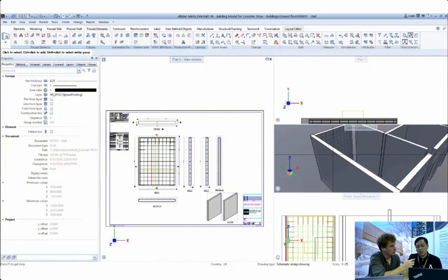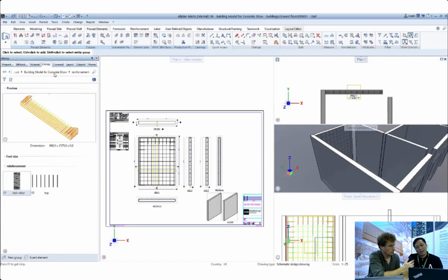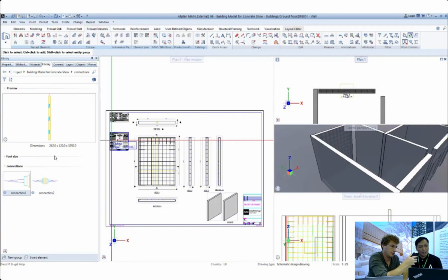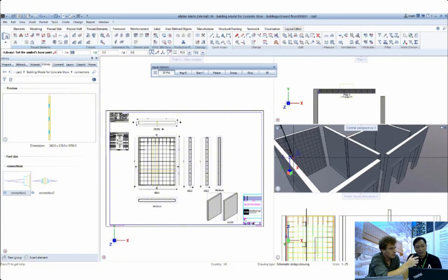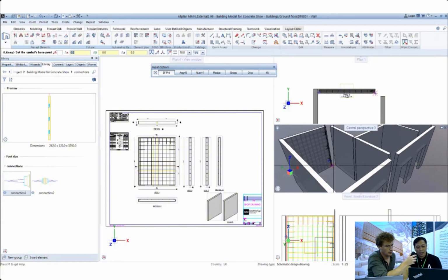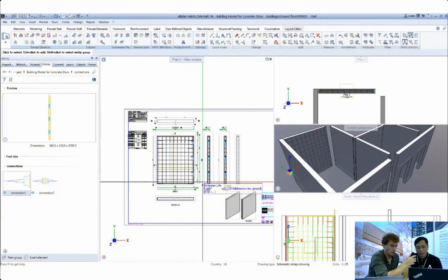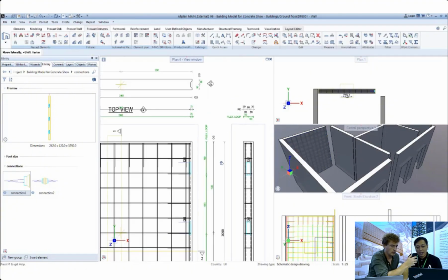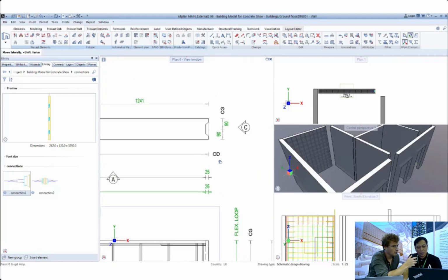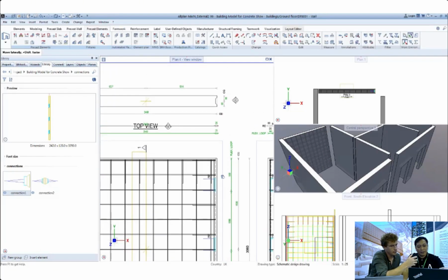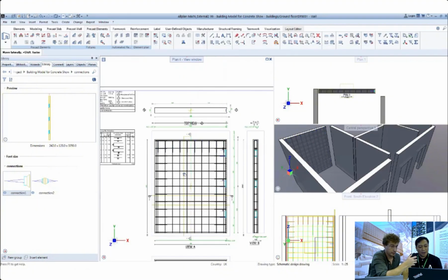We're going to place the fixtures, let's say for the connection on the sides. So basically, I presume from the model, we have a column here. Yeah. So we can define it. For this case, I already have it saved in the library. So maybe I can just use this. Okay. And then here, I will just pick this part, and instead of the shop drawing, I'll put it on the model. So I'll just detect the correct reference point here. And then as you can see, it automatically shows on your element plan together with the cutouts, which are defined here as well.